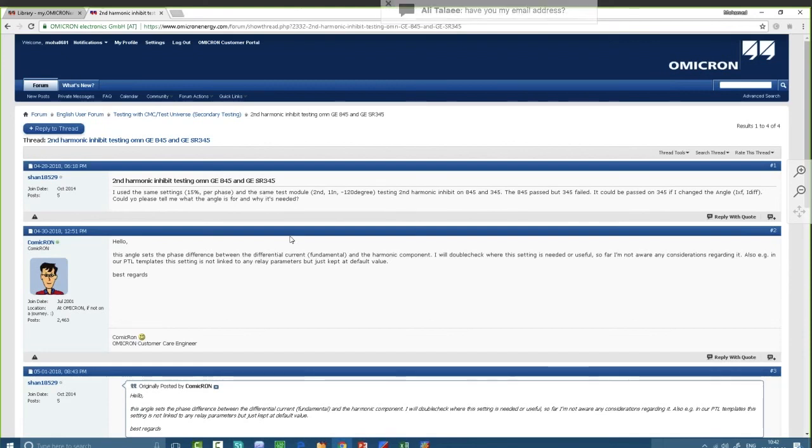I think I got a question from Mr. Haroon. Just 1 minute, Mr. Haroon. Is the PTL file needed for calculation or changing the K factor? No, nothing. If you import the exported files from the relay, it doesn't need anything, because everything is linked automatically. But in case you need to draw it manually, at that time you need to modify and enter it manually.